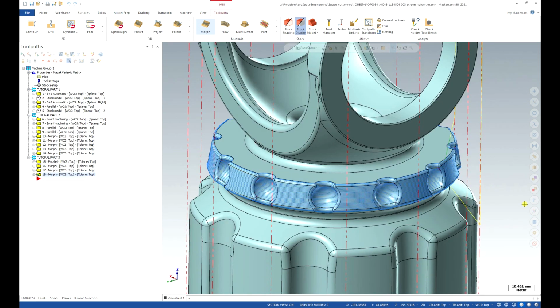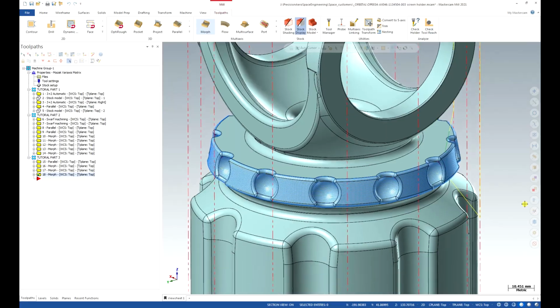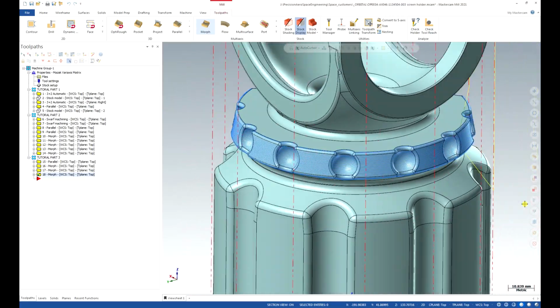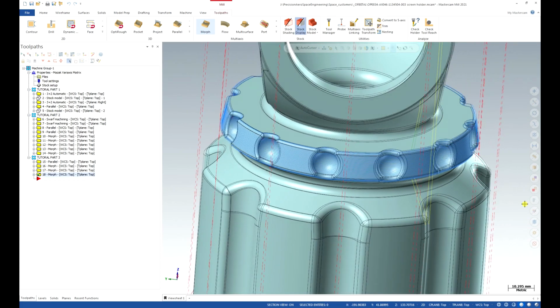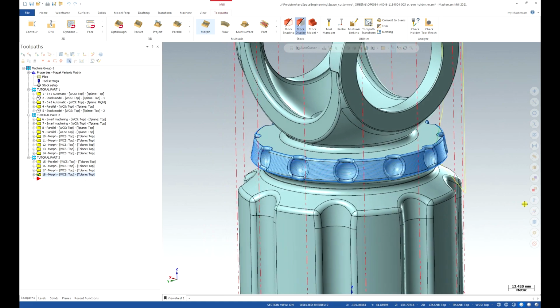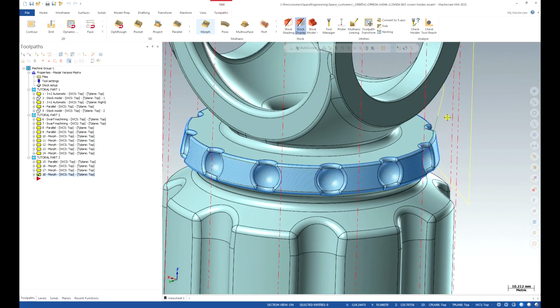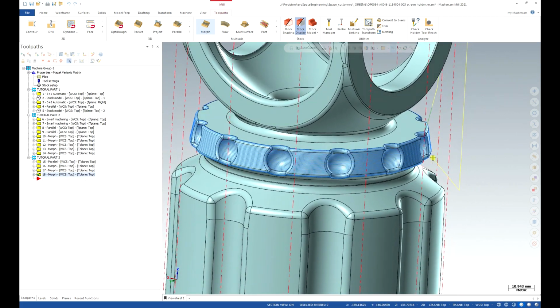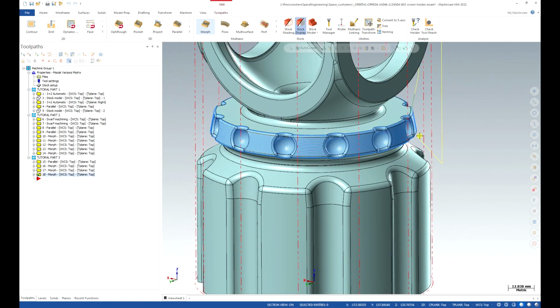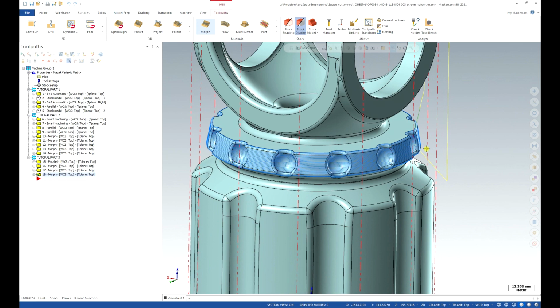Okay, and I see visually the toolpath looks really clean and nice, but I know straight away that the finish point is outside my A-axis movement range. The start would be fine, but that will kick off outside my A-axis range.